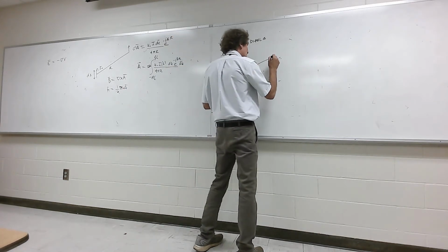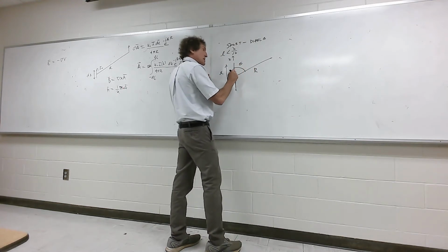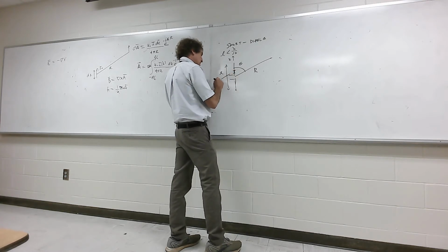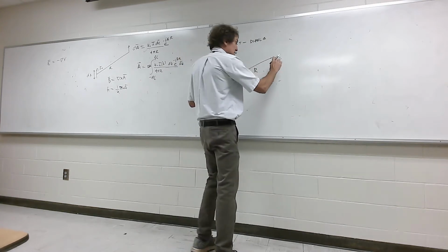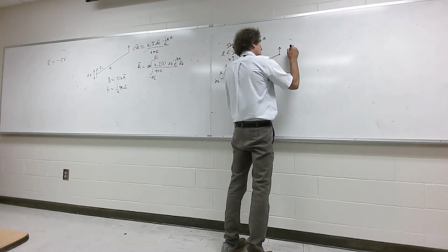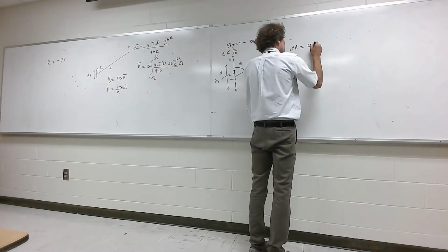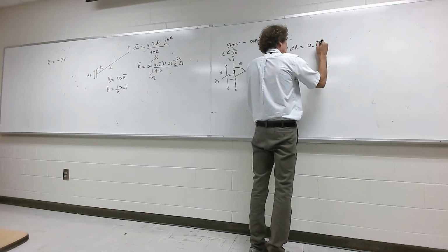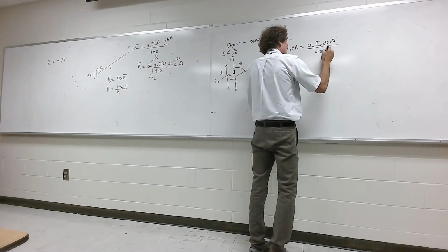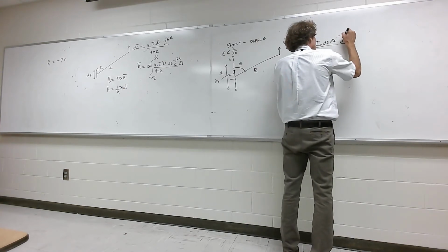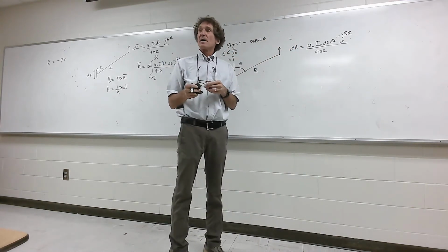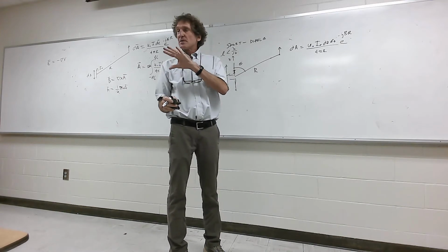Distance r away, and the first thing I have to do is, if I have a little differential chunk of current here, that can be dz thick, and it has a value of I, then I can say the differential magnetic field out here has to be in the direction AZ. So the differential magnetic field for this would be mu 0 I, it's going to be the same everywhere, so just I, times dz AZ over 4 pi r. Then it's going to have the form e to the minus j beta r. Now that's the differential field. To get the total field, I'd have to integrate. I want you to listen to this. Some of this stuff you have to take on faith.